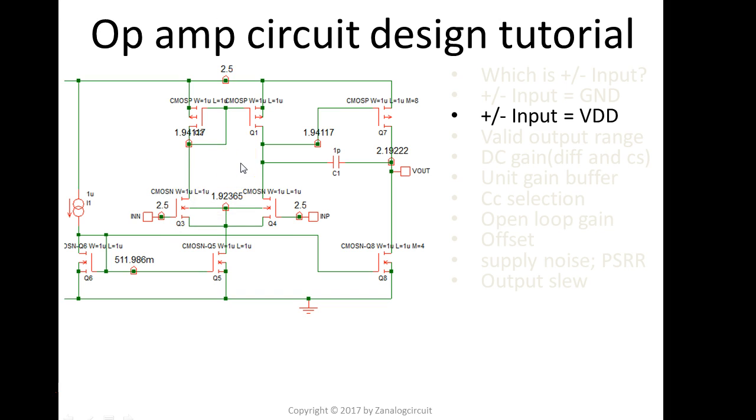But in reality, this is not really preferred. The reason is the minute you try to increase the L over W ratio, or to decrease the W over L ratio, for the same amount of current, you lower the gm, right? As we talked about in the other video, for the input stage, for the sake of offset and gain, you want to maximize its gm instead of minimizing. So how should you do it? Find a way to make Q3 and Q4 be in the saturation region.